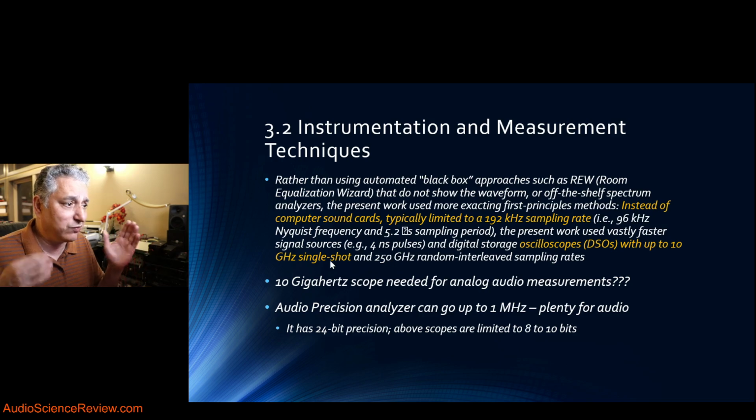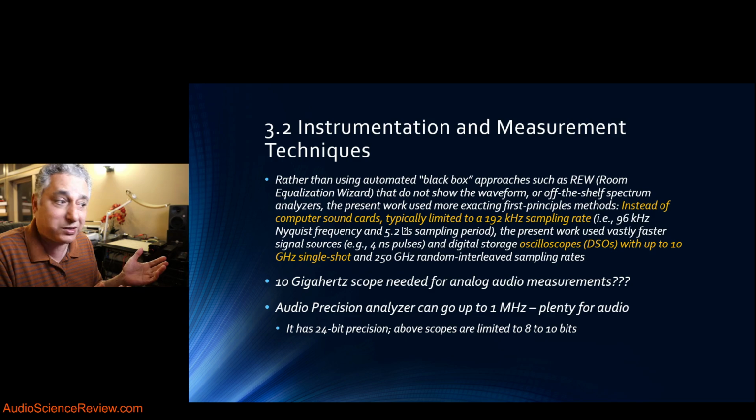Whenever you get a chance, you want to measure something with the least amount of bandwidth and the appropriate tool. So I'm able to dig way deeper into noise floor and distortion with my analyzer than you ever can with this. Now, if you're measuring a cellular transmitter inside a cell phone that runs at 2.5 gigahertz, whatever, then you have to use this kind of scope, and you give up dynamic range. But fortunately for RF work, you don't need that kind of dynamic range.